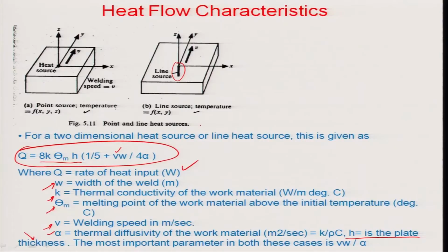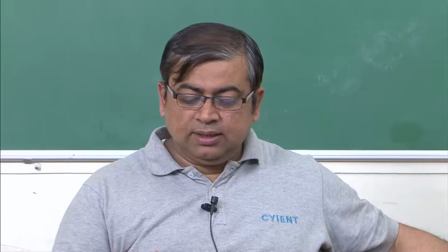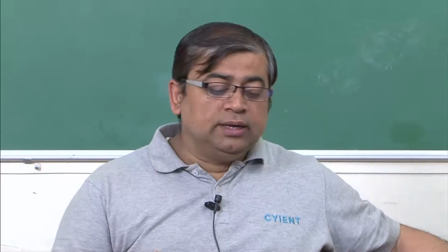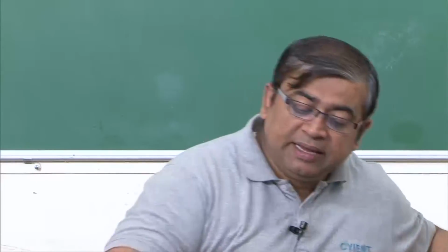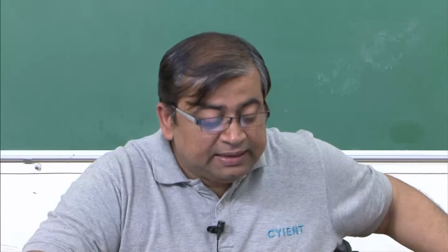In this case, we really do not assume any other losses, and we assume all the power is being applied in order to melt the weld, because the power delivery is a huge power, and although there are some chances of heat dissipation, we are trying to consider that to be negligible in comparison to the actual melting and the application of the liquid metal to the weldment.